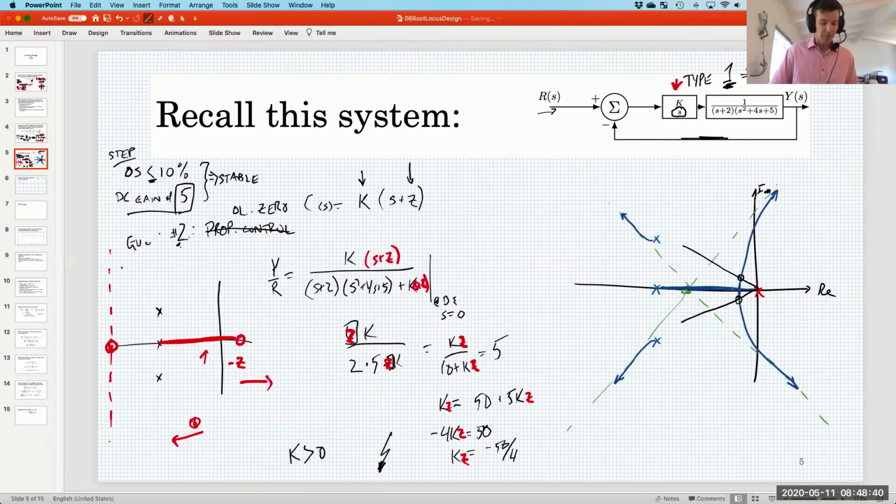Okay, so we went through a short list. We started simple with the proportional control. Well, we started with what was given to us, which was integral control. And then we cooked up some make-believe requirements and found out that the thing that was given to us wouldn't meet those requirements. So we said, let's try something else. And my recommendation is to start simple, because simpler is better in some respects, it's fewer things for you to design. And as long as you can meet the requirements, then why overcomplicate things? However, a proportional controller didn't meet the design requirements, so we had to step it up.